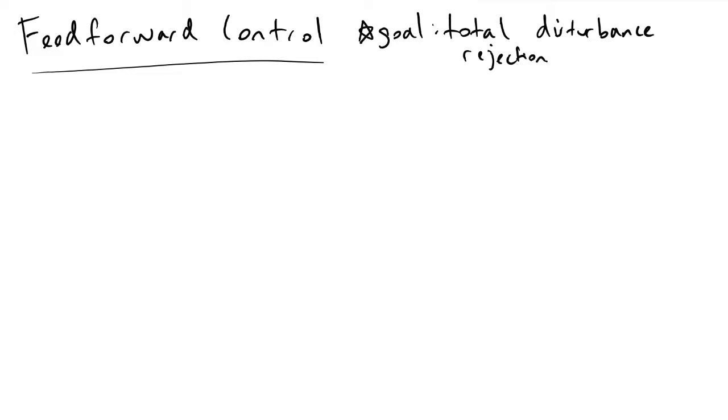Our controlled variable will be different from its set point for a certain amount of time, or in the case of P-only controllers, for instance, we may have offset. And so if we wanted to completely reject disturbances in our system, we will turn to feed-forward control. And there are some key things to note before we start to dive into the control block diagrams involved.